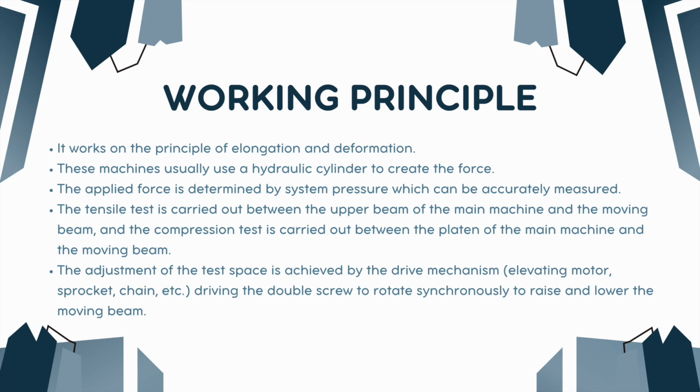So the working principle is very simple here. It works on the principle of elongation and deformation. These machines usually use a hydraulic cylinder to create the force. The applied force is determined by system pressure, which can be accurately measured.